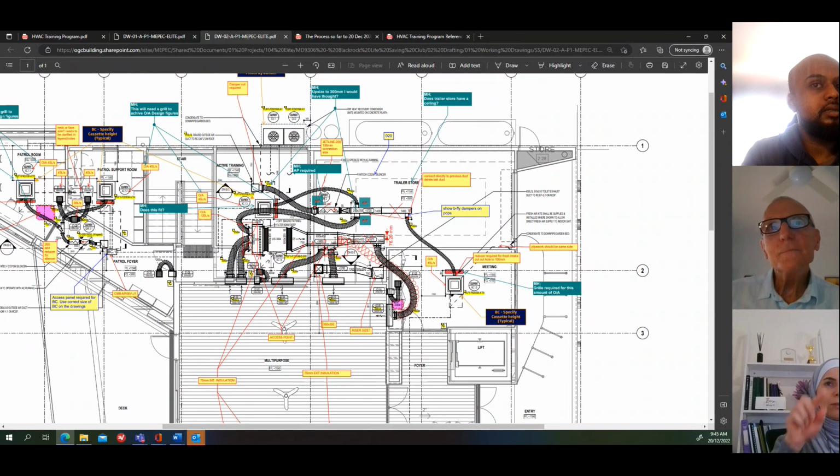Should be somewhere inside. Correct. So the actual airway size, the duct size, if you like, that the air has to pass through is less than 600 by 450 in this case. Because it's internally lined. Yeah, less the internal insulation. So that's important to see the difference, because when you look at a design drawing,